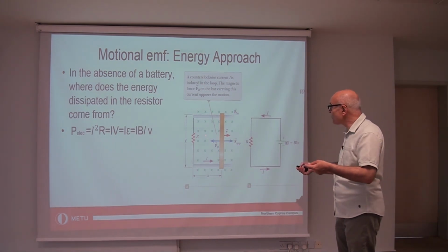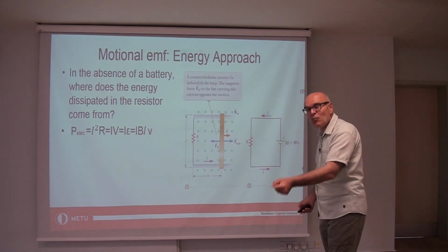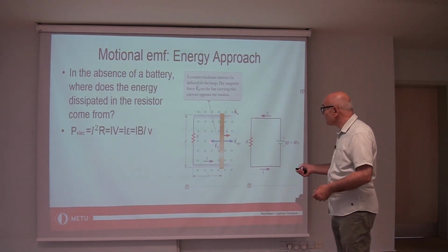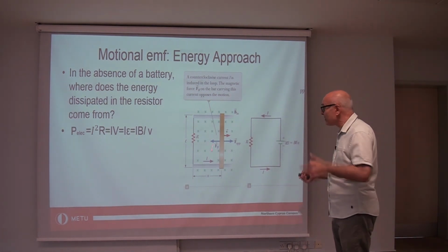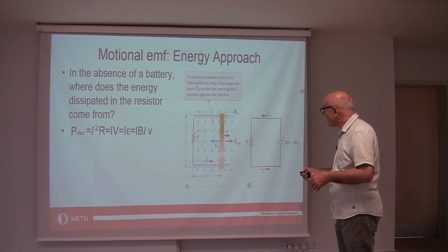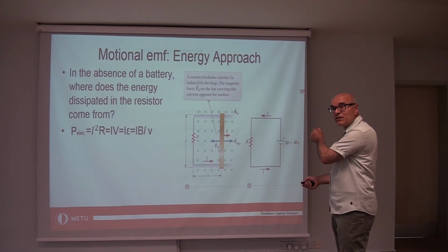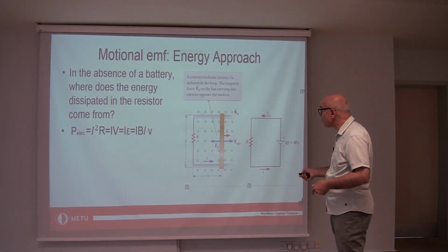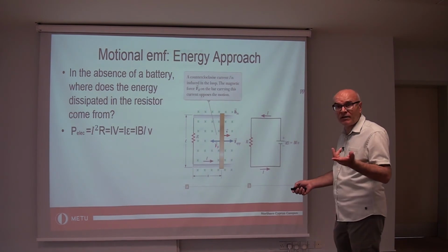So in the presence of a magnetic field, moving this bar is like moving a bar in water, for example. You will feel a resistance, due to the presence of the magnetic field. And this resistance is nothing but the magnetic force that acted to the left. So we know now that we have to apply a force here to maintain the constant velocity of this bar as it moves to the right, so that it continues generating this current. So we have an applied force equal and opposite to the magnetic force, so the magnitudes are the same.